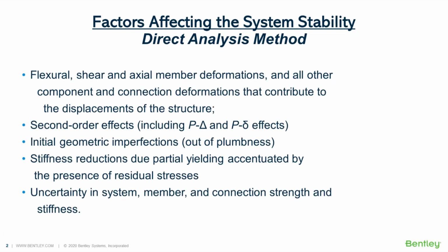So the direct analysis method addresses all the requirements as mentioned by the AISC code. Let's discuss them. First one is quite obvious, as all the deformations and the displacements have to be considered in the analysis, and STAAD takes care of all those deformations and displacements while performing the analysis. Second is the consideration of the second order effect by considering the P large delta and P small delta. Now that is also being considered by STAAD while you are performing the direct analysis. While you perform the direct analysis, STAAD at the background runs the P delta analysis.